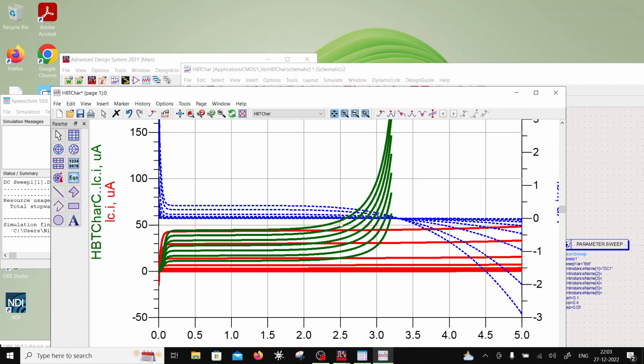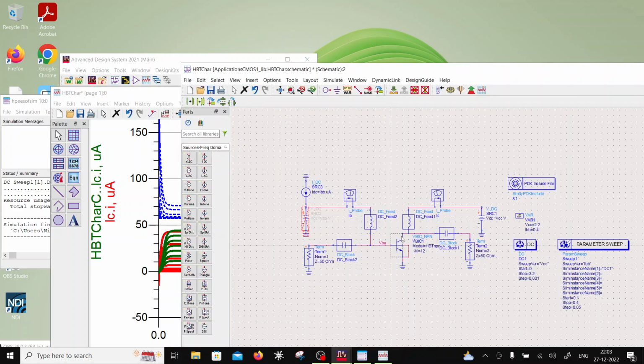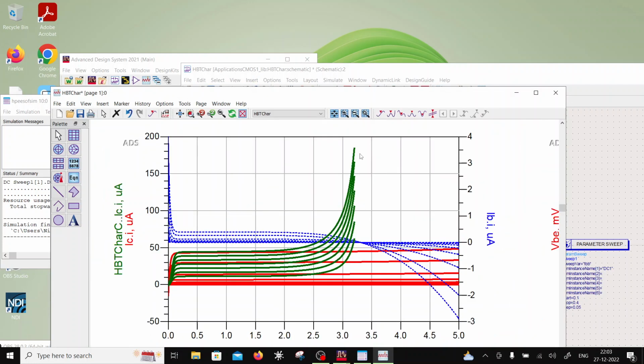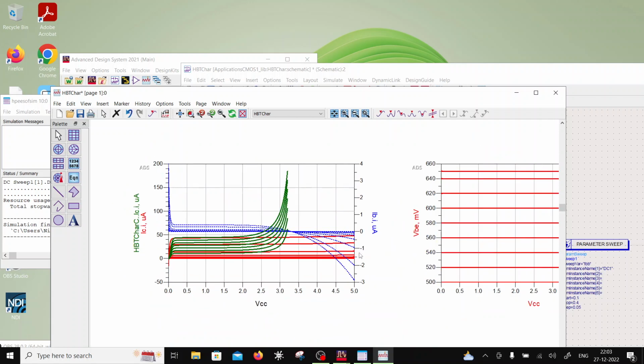because now the leakage current of collector base breakdown is flowing into the base emitter junction rather than being absorbed by the base terminal as in the earlier case, and this causes the leakage current to be amplified by beta, and this is like a positive feedback which causes the avalanche to take place at a much lower voltage. That is why BVCEO would be BVCBO divided by nth root of beta, or it will be much reduced. And the base currents are going to be positive here, right?